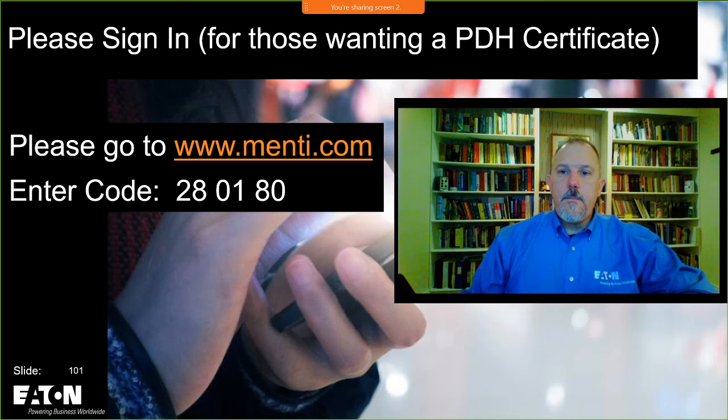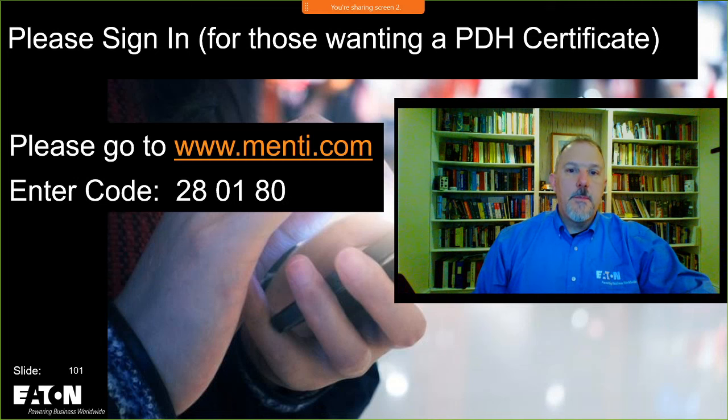Absolutely. All right. Well, it's 2:03. Some pumps that are cord connected have a leakage current test. Beautiful. 100 milliamps. I agree, Robert Victoria. 100 milliamps is still pretty good protection.